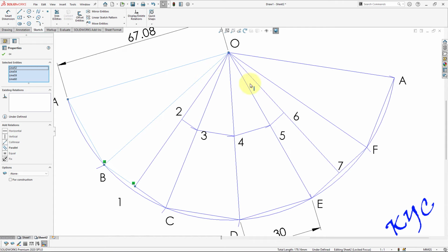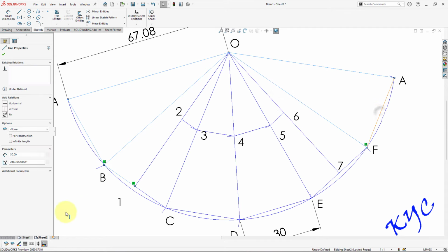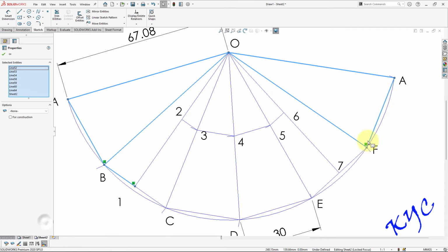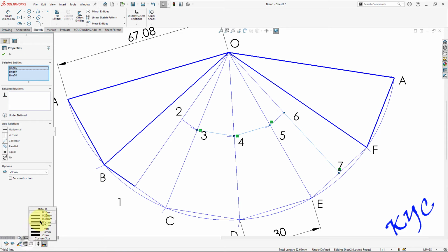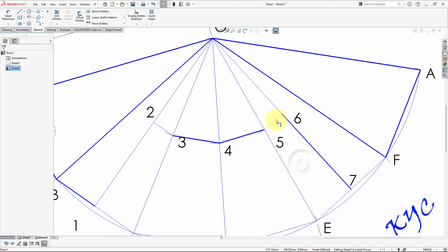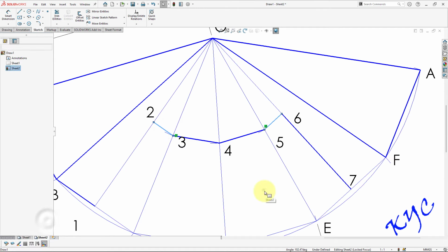Okay, this I have not trimmed yet, so let me first make this 0.5. Here this portion is thick, this is thick, this is thick, make it 0.5. Here if you observe, this also I can select and make thick, not a problem. Hold the Control key while selecting more than 2 elements.